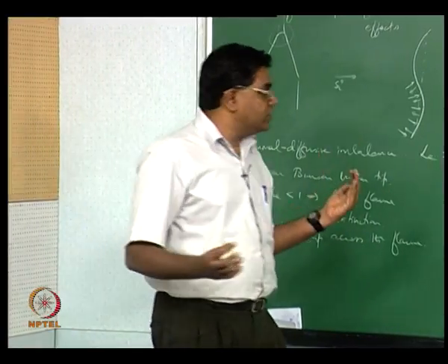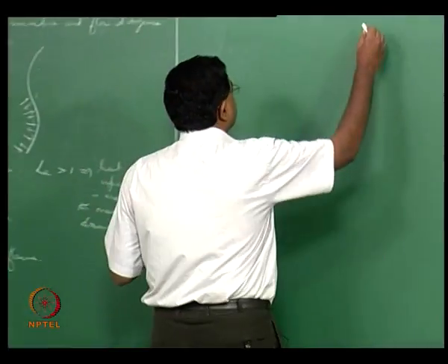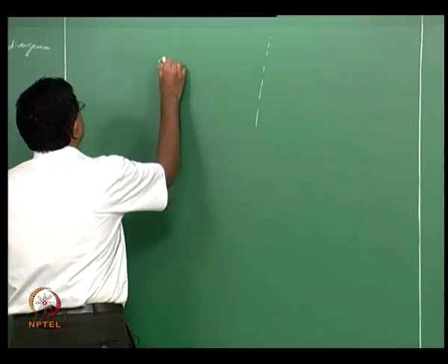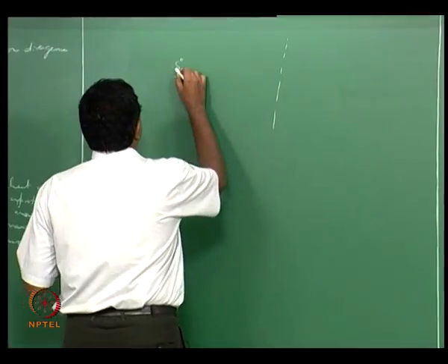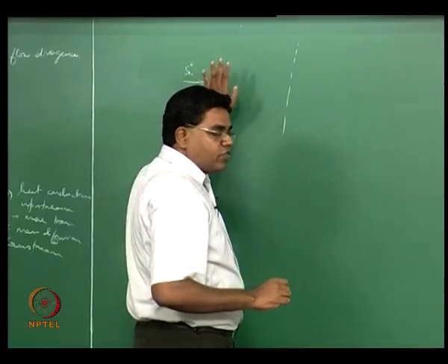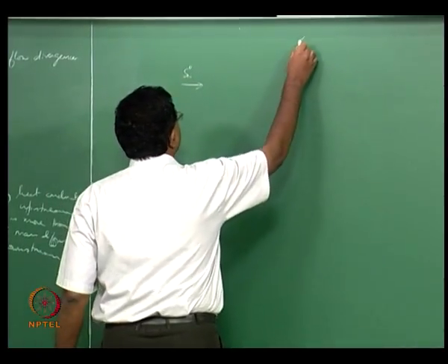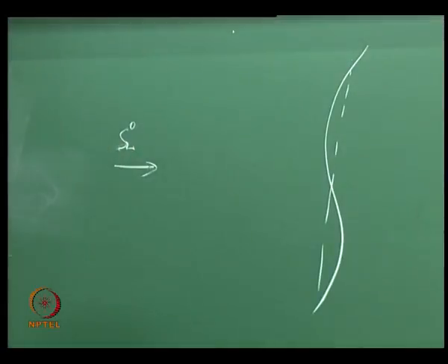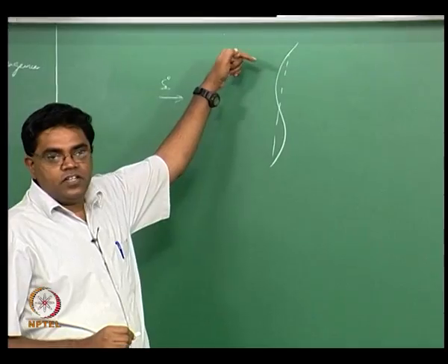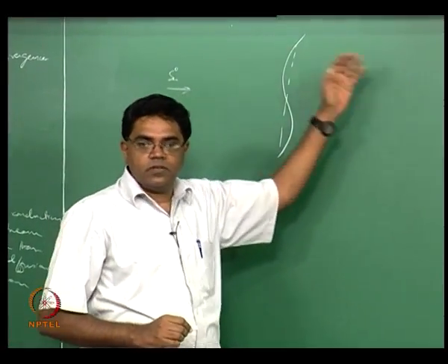So we still go through the same idea, that is you have a nominally flat flame with an S_L naught, but then you are beginning to think about the fact that the density of the products is going to be less than the density of the reactants and perturb the flame to be non-planar. As a consequence of the density difference, local mass balance dictates that the velocity should compensate for it.